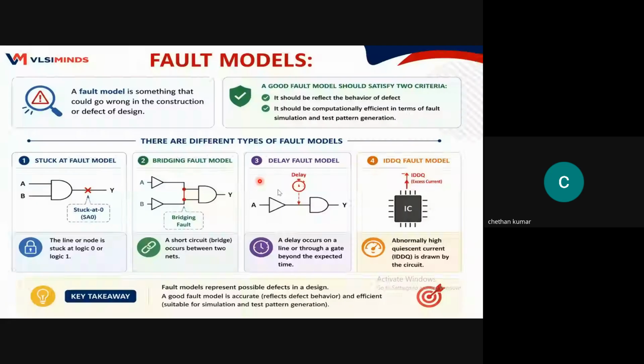At speed is nothing but transition delay faults. So separately we'll generate and separately we'll deliver to the ATE. Even the ATE team will test them separately, stuck-at separately and transition faults separately. For the transition faults, whatever the STA team closes on all the timing, you need to take a file from them. SDF, correct. Yes, SDF files we have to take from them.